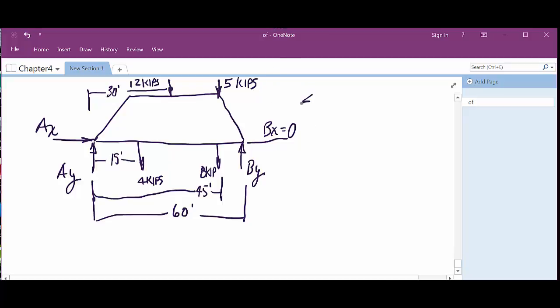So sum the forces in X equals 0 equals AX. Is that right? If one of those forces on the top of the truss is at an angle, then we would need the height, right? Yes. If one of these forces was at an angle like in that example problem, you'd have to have that height because you have an X and a Y component to deal with in the form of a moment. AX wouldn't be 0 in that case. But in this case, we're fine.